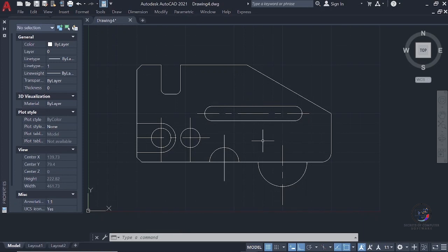But there are other lines that are not center, they are almost continuous lines. You can type LTS on your keyboard and then click enter. This is to specify the scale factor of your center line. Let's put it as maybe 5. You can see my lines are almost continuous. Let's put 10. It is still continuous. I have to reduce it. Let's put it as maybe 0.3, 0.3, and then click enter. You can see this is a little bit better. So cancel the